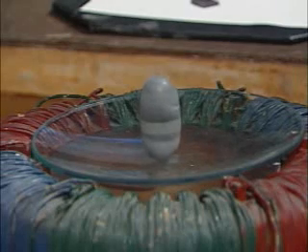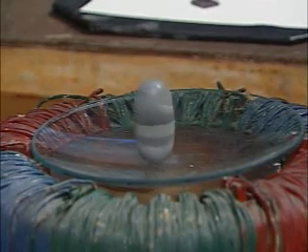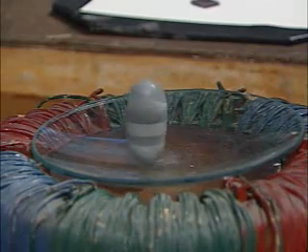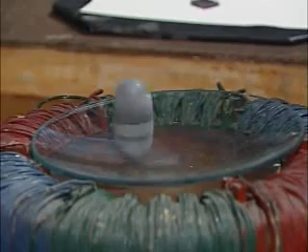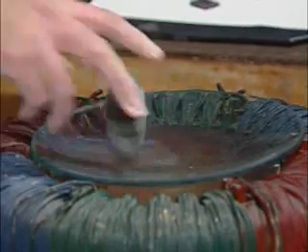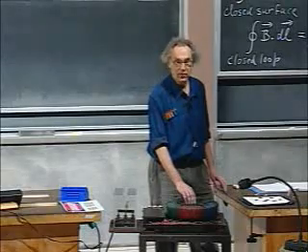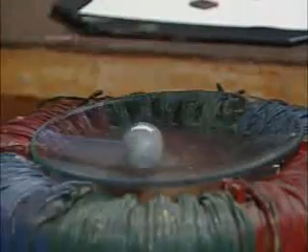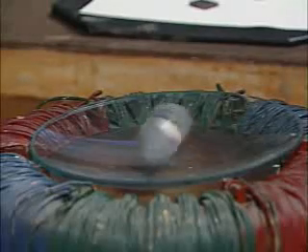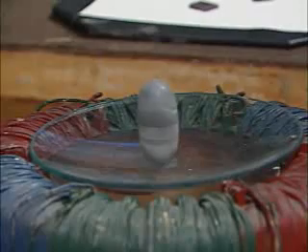I have actually tried to measure the rotation rate. It's only a little bit under 3,600 RPM. 3,600 RPM would be 60 Hertz. It's very close to that. If I spin this object in the direction in which the magnetic field is not rotating, then it says, sorry, no way. It just reverses, because the magnetic field is going to slave it in the direction that it wants it to go.